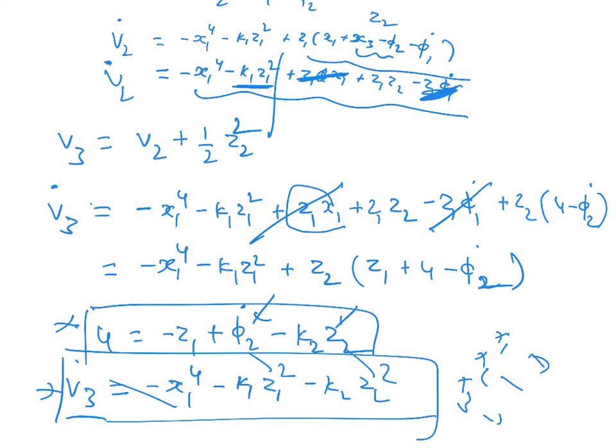Sliding mode and adaptive: how do you show that something is negative definite? By choosing u. Choosing u equal to minus something times sign of s makes it sliding mode. In adaptive, you also have to get the parameter estimated, so adaptive will be different.